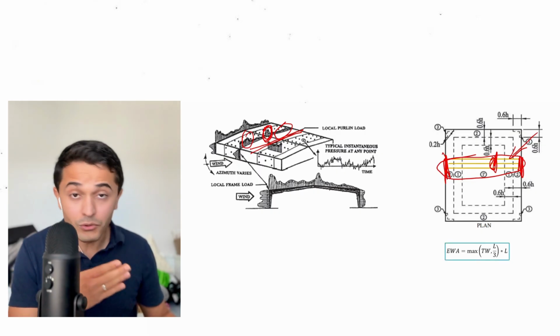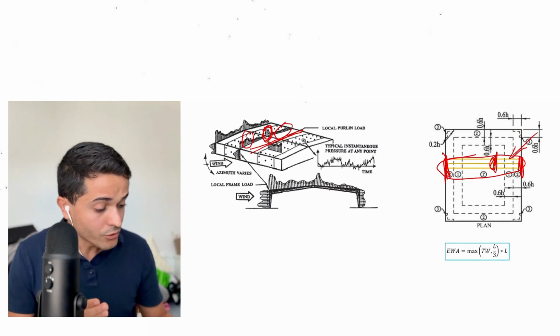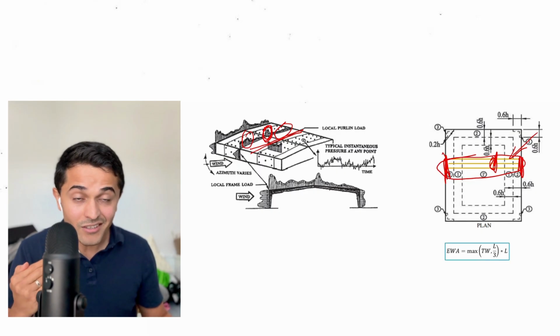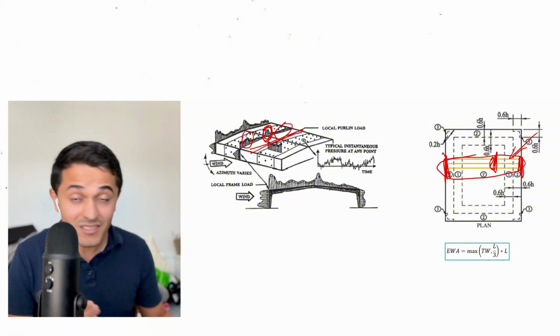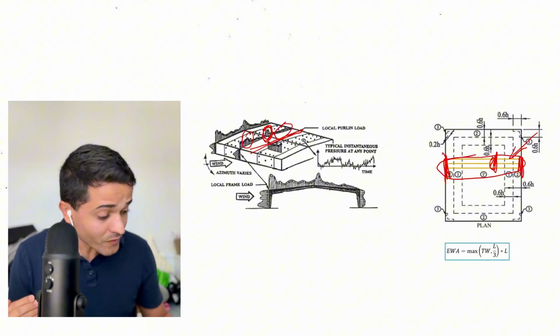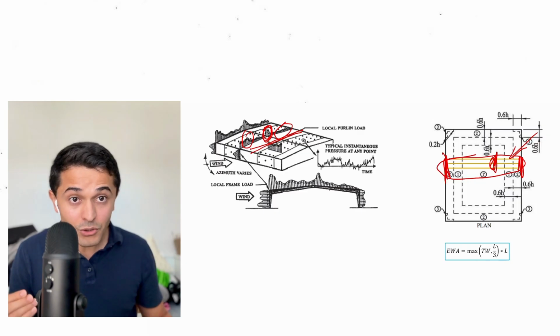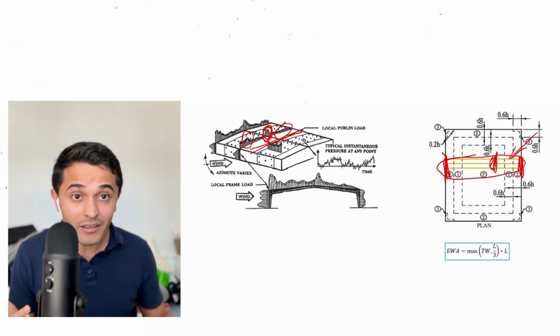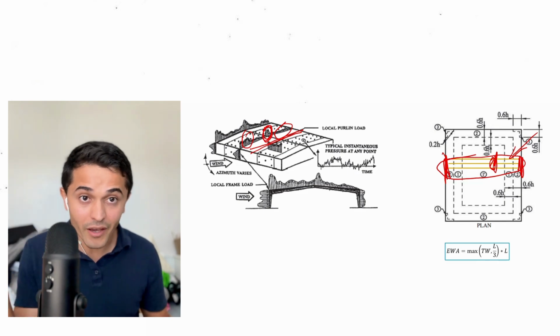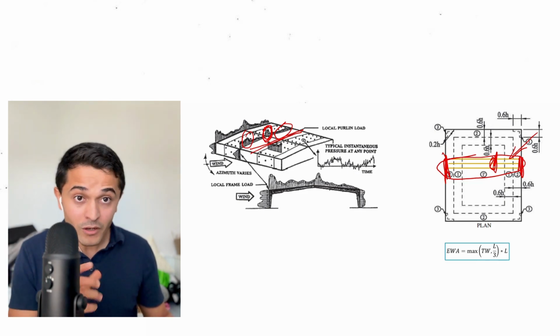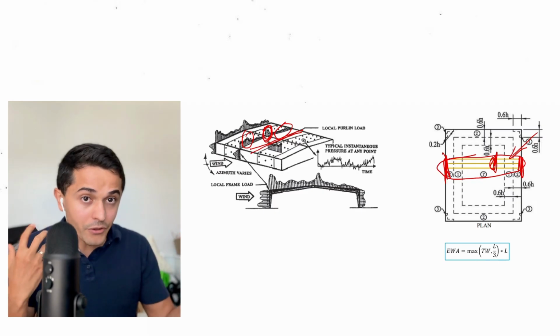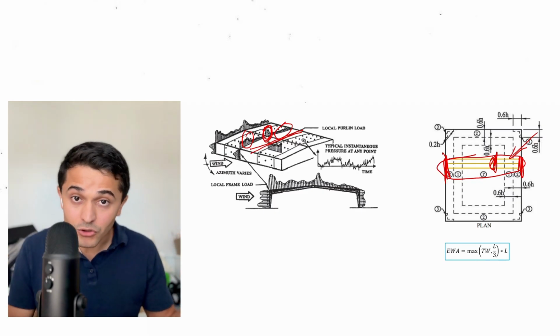You'd use your formula, see your tributary width, which let's say is 2 feet, and then the member is 60 feet long. You would have 2 times 60, that's 120, but then 60 times 60 over 3 will be much larger than that, right? Therefore, that effective wind area is going to be greater than your tributary area.